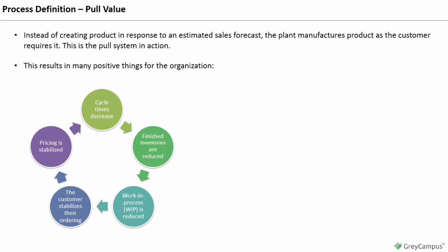Most mass production manufacturing firms are in the push production mode. Each operation produces as much as possible and sends it on to the next operation. The goal is to maximize machine efficiency with a maximum amount of in-process inventory sitting around the plant. Contrast the above manufacturing firm with the factory that is dependent on the pull of the market. The receipt of a customer order initiates activities. Each operation produces parts as needed through a signal from downstream. There is a minimal amount of WIP in the process stream.